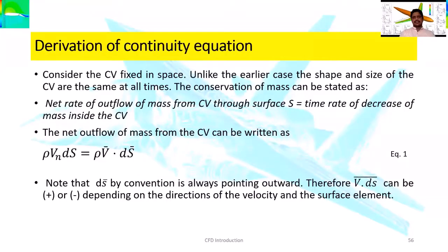of the continuity equation. To derive the continuity equation, what generally we'll assume is that, let us take a control volume which is fixed in the space, as you have done in your earlier courses. So of some arbitrary shape and size of a control volume, which we will take. And generally what is our conservative form of the equation is that the net flow out of the mass.